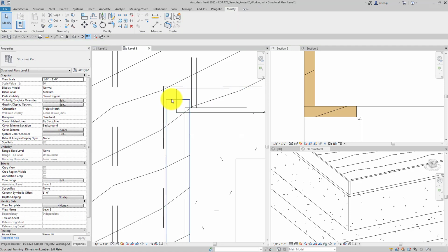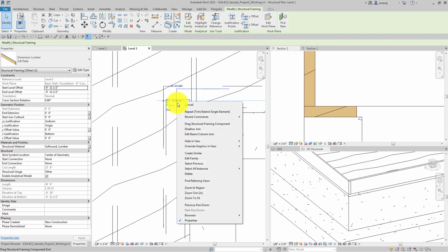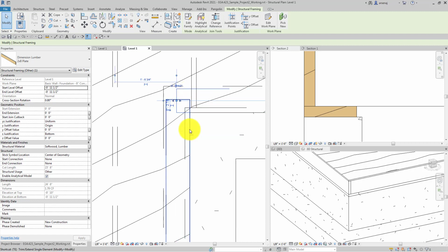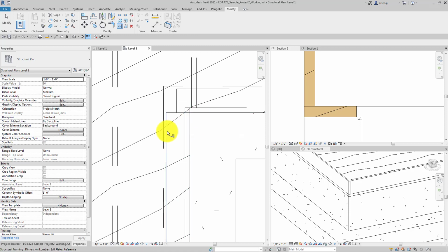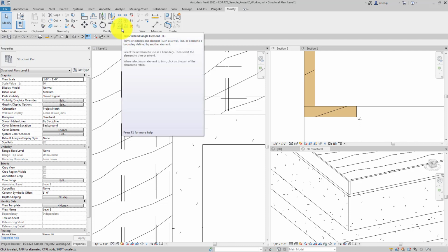So what I'm going to do, though, my last effort, because usually I just don't want to mess with it long enough. I know lots of ways to force it. So if you select a beam, beams are set to auto join, so they typically are set to join. If you hover over this last node or grip, right click and disallow join, then we can get them to lap correctly, because now they're not going to want to join with each other, but that's okay. Now we can trim, extend and get them to join correctly.